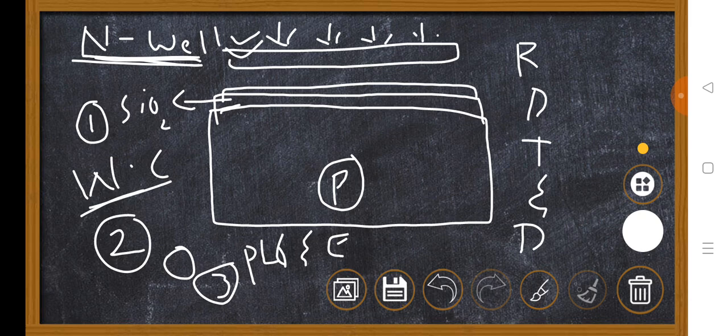Wherever required, here we require two places. Why? Because one is for the well. Which well do we require? N well. The N well should be present at this position, right? Therefore we have to cover here, and we have to allow here, and we have to cover here, and similarly here we require a gate. Therefore we have to cover here. That means we have to open two windows: at this position one window, at this position another window. Is it clear? After photolithography and etching, what is the acid we are going to use in etching? Absolutely, hydrofluoric acid.